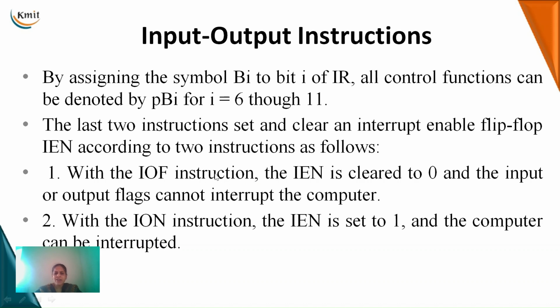Whenever the output register has completed its task and is free, it can take the next character from the CPU, and it can interrupt the computer by means of an interrupt enable flip flop. Similarly, whenever the input device has a character to input, it places it into the input register, and whenever it wants that information transferred to the computer, it can interrupt the computer through the interrupt enable flip flop.